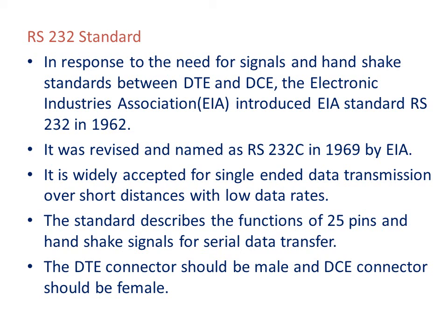This standard describes the functions of 25 signal and handshake pins for serial data transfer. It also describes the voltage levels, impedance level, rise and fall times, maximum bit rate, and maximum capacitance for these signal lines.